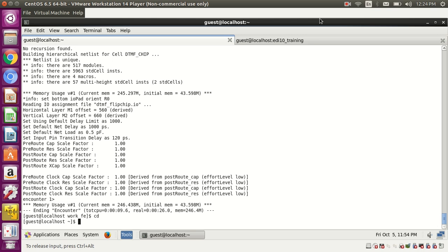So the RTL guys will not write the full RTL code, but they'll create the overall modules and the blocks it should have. Then the synthesis guys do a rough synthesis. Not every logic is useful and not all things are connected, so some flops will end at some point. So it's a rough netlist.